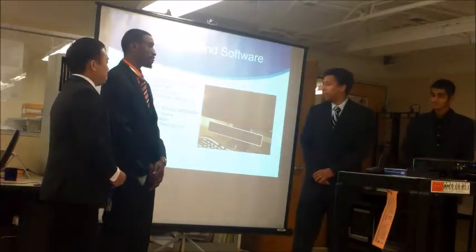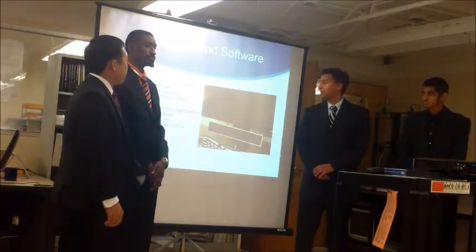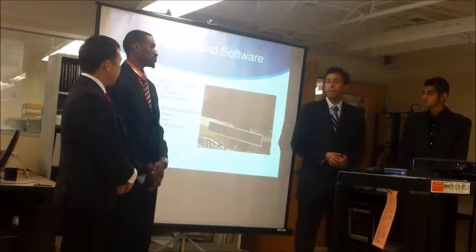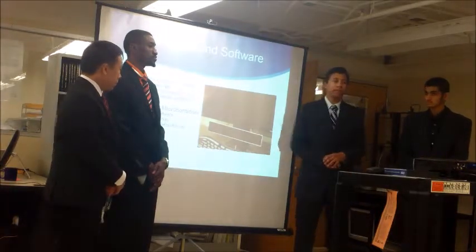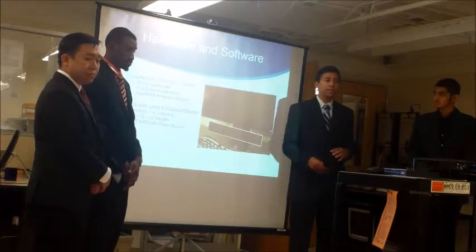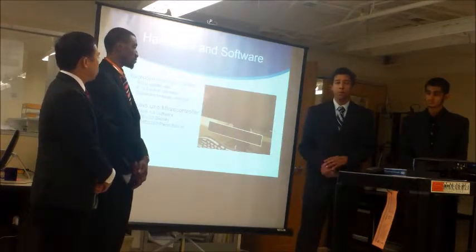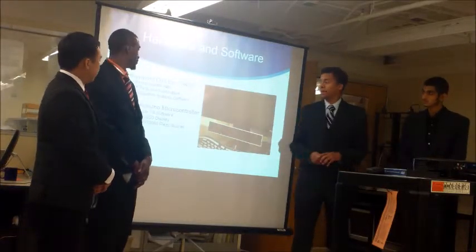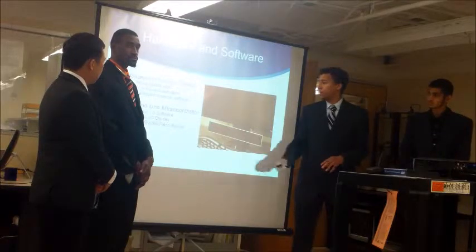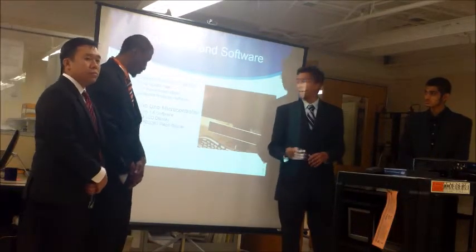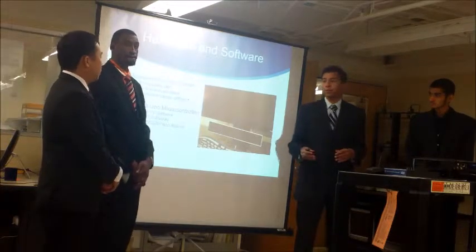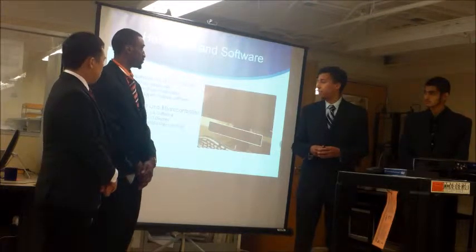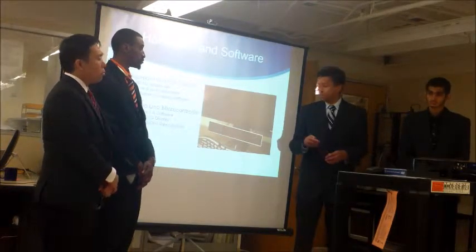Thank you, T. Our hardware for this project is the Gaze Point GP3 mounted eye tracker. As you see here, it uses sensors within it to determine the gaze detection and the pupil of the subject, whoever's going to be driving in this case. It has a 5-point or 9-point calibration. And we're also going to be using the Arduino Uno microcontroller for our alert system to take inputs and send outputs through our visual and audible displays.